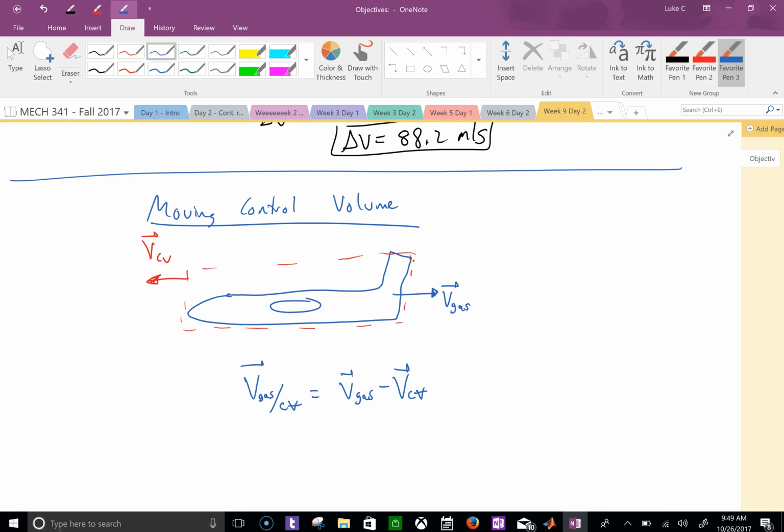So just think of it this way. If the plane is going that way, positive direction, and your gas is going in a negative direction, right? If you're the person sitting on this nozzle here, it would look like it would be coming out fast, right? Because it would be a negative and a negative. You would add them up, okay? Because one's shooting this way, the other's shooting that way.